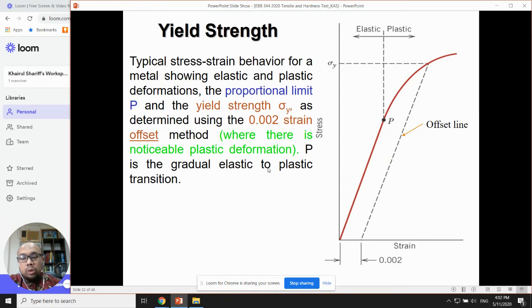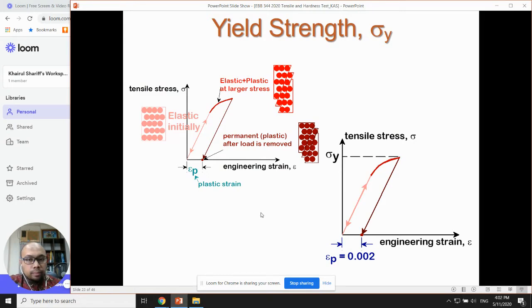You select the tensile mode and perform the test, and then you get this graph, and you can calculate the yield strength value for this metal. You can use the 0.2% offset from the strain. So it's really important.